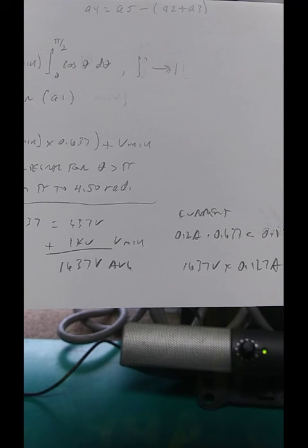So the voltage rating for the capacitors, for example the plate blocking capacitor, where capacitors are rated at DC plus RF swing, that's gone down considerably, and that means the components are a lot cheaper, smaller, lighter, and might just be able to use off-the-shelf components. So there's a run-through of the plate calculations.